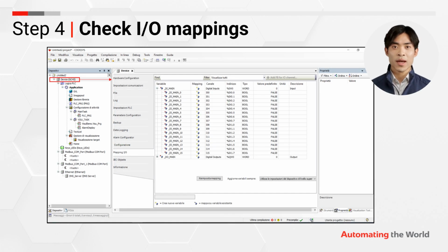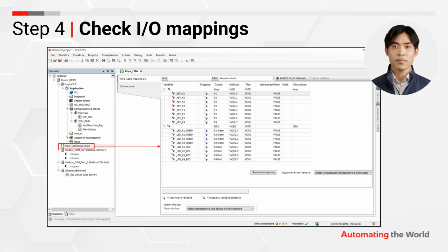Step 4. Check I/O connections. Still in the device section, go to the I/O mapping subsection to find the mapping of the digital input and digital output signals that we can use for addressing from the PLC and HMI logic. The mapping of the key LEDs signals can be found in the same section of the project tree. The addresses are divided between the K and F key inputs and the outputs for the K key colors, red or green. From the display management section, the K and F keys can be associated with specific actions.